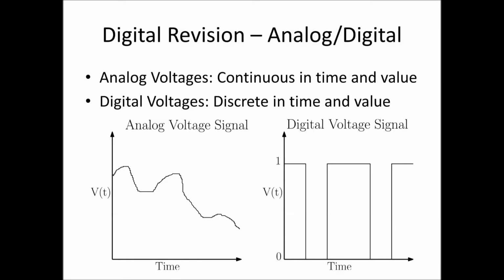In this video, we'll look at how we can create analog-like signals from our Arduino using a technique known as pulse width modulation, or PWM. From earlier videos, we know a digital signal is a discrete voltage, and typically 0 or 5 volts, whereas an analog voltage is a continuous voltage. It might be, for example, 2.5291 volts, and so on.